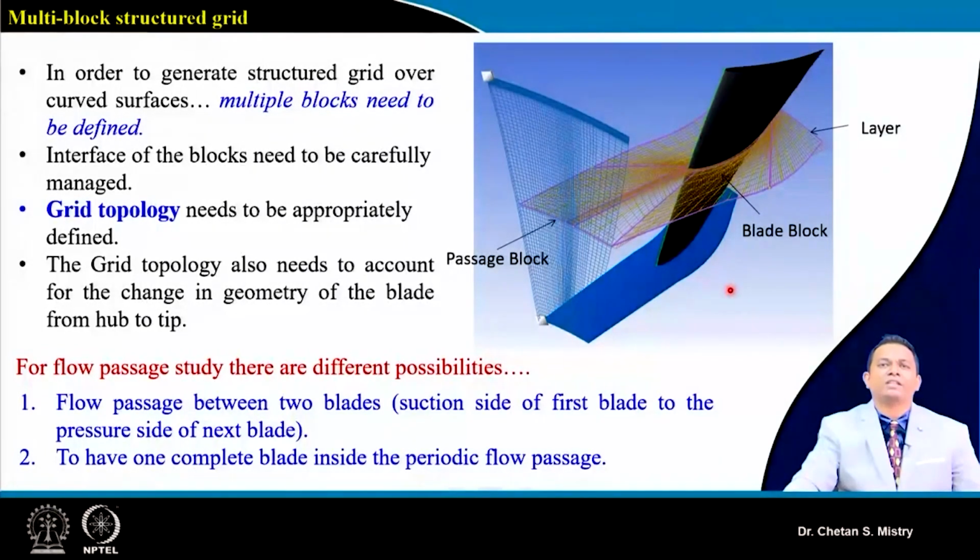Mostly when we are analyzing the rotor and stator configuration, we opt for this second option. It says complete blade inside the periodic flow passage. So this is my periodic flow passage in which we are putting our blade.